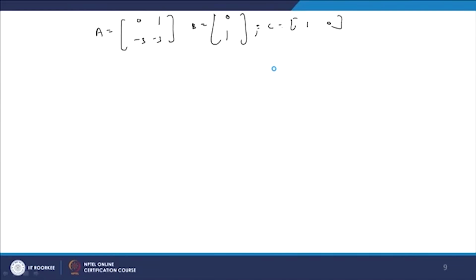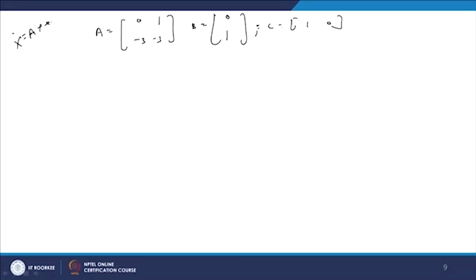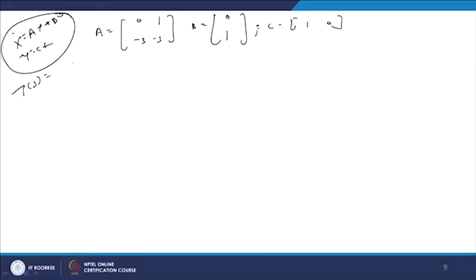Why? Because here our main concentration is on the closed loop plant, that is our model x dot = Ax + Bu, y = Cx must be in a closed loop for using method 1. That is why here we have shown the state space model for a closed loop plant, that is we have written the equation A, B, C, D from T(s), that is A, B, C, and that plant is G(s) upon 1 + G(s).